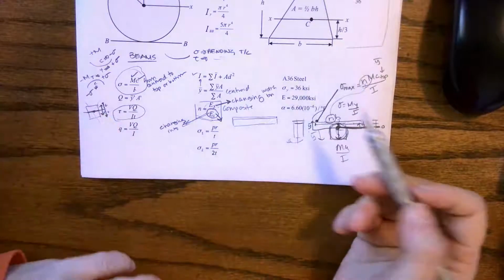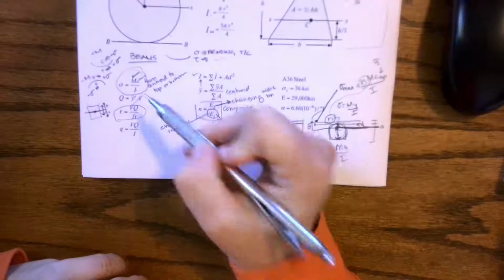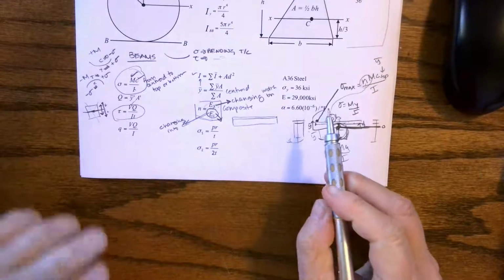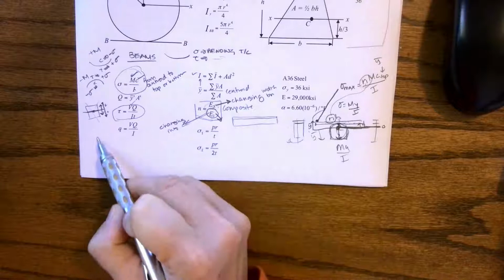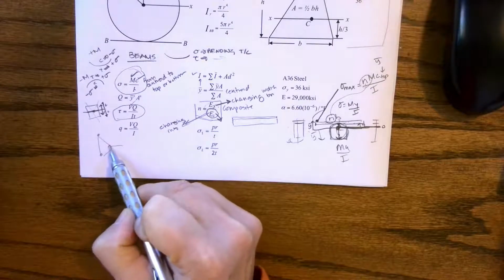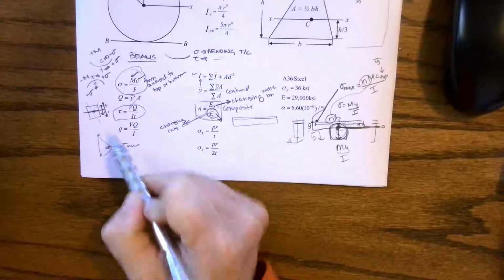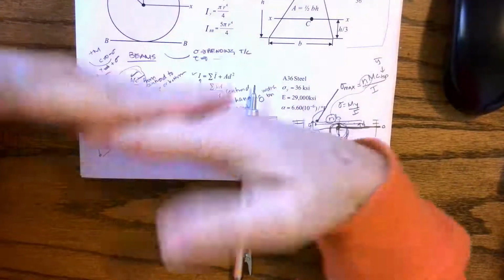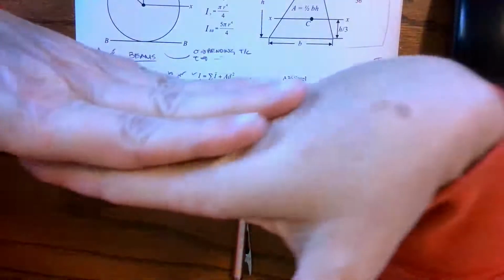So when we have a shear diagram, this comes from the moment diagram, this comes from the shear diagram, and our shear stress is going to be 0 at the top and bottom, and maximum here at the center. So it's like opposite our bending. And that's because as we're bending, if we didn't have these pieces combined, they would end up sliding against each other to make that curve. When they're combined, we're having to hold them together. And so that's why at the middle, you're going to have that largest shear stress, because it's the largest area.